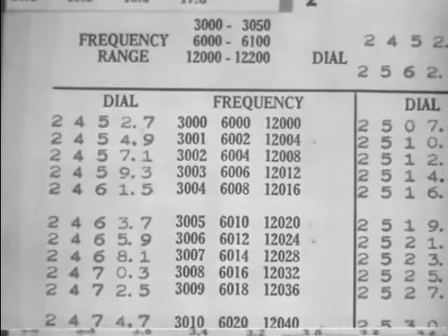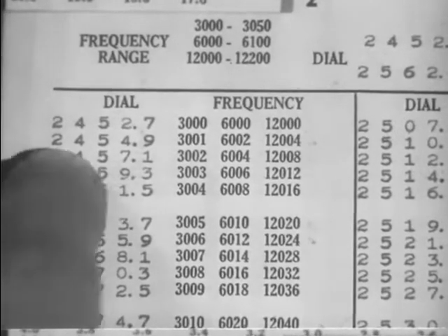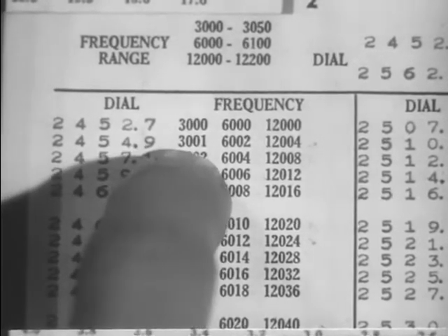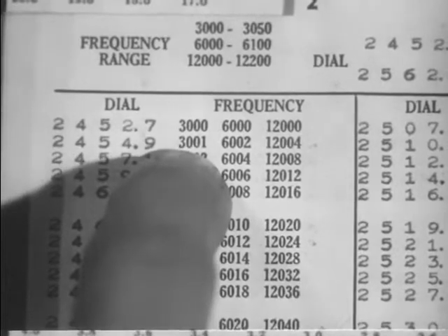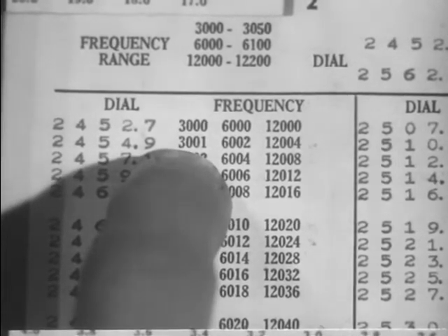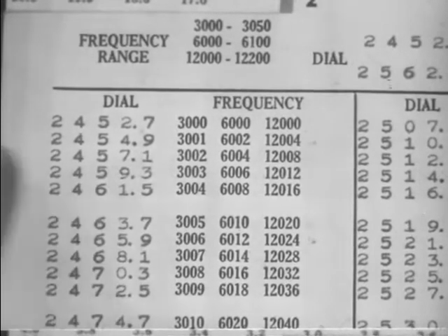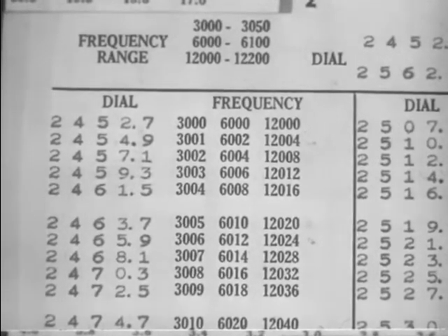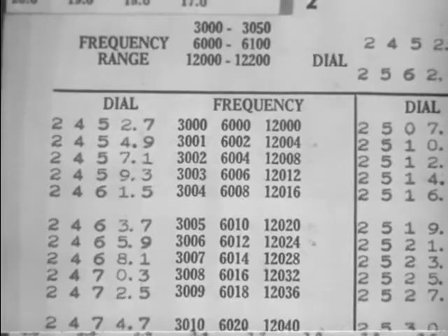If the meter and generator dial readings agree, the generator is in tune. A tolerance of 1 or 2% is allowable on most signal generators. Of course, this procedure must be accomplished on each band to check the accuracy of the entire range.